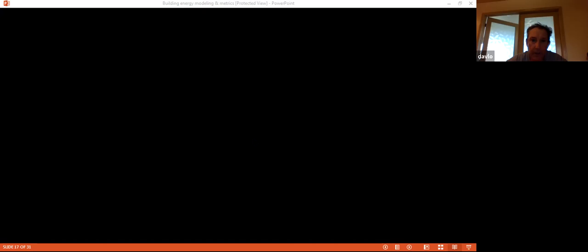Yeah, sounds good. All right. So I kind of agree with them. We have the saw stops. And I talked to the students that the saw stops are probably the most dangerous equipment in here because they're the safest. They're the safest because they have devices where, if you have your finger or your hand in the way, the blade is supposed to drop down and not cut you. But when students leave our shop, where it's nice and safe and kind of a fantasy land where everyone is trying to be protected, they go back to the real world and get on their old rickety $300 table saw or whatever it is. They don't have the bells and whistles. But they're so used to using our equipment, they tend to get their fingers closer and closer and are more and more complacent with the safety equipment. And when they go home, they try to do the same thing and they cut themselves really bad. That's a problem for us. A big problem.